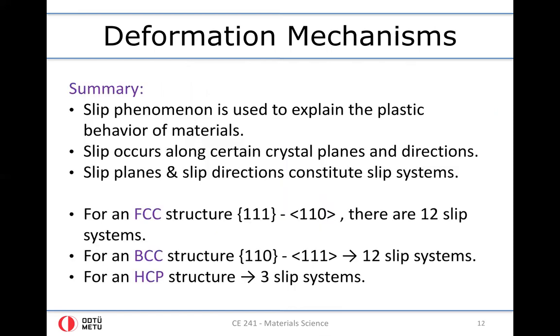So just to wrap up, the slip phenomenon is used to explain the plastic behavior of metallic materials. Slip occurs along certain crystal planes and directions that are densest in terms of planar and directional densities, because the denser the planes and directions, the easier it becomes for atoms to hop, and therefore for dislocations to move.